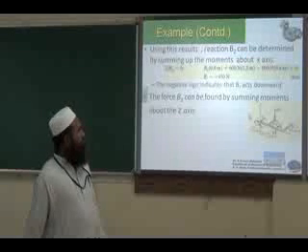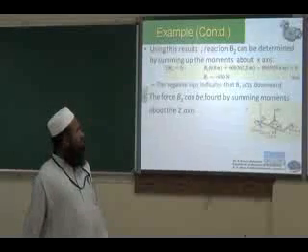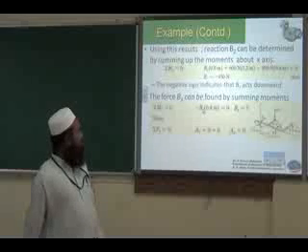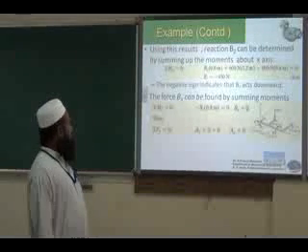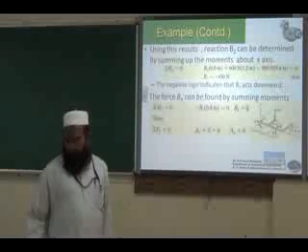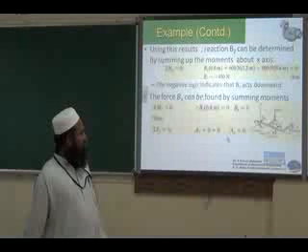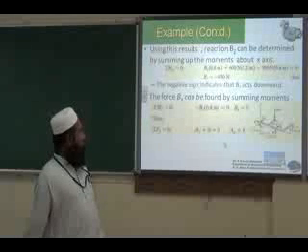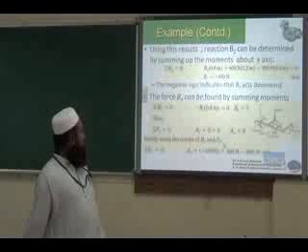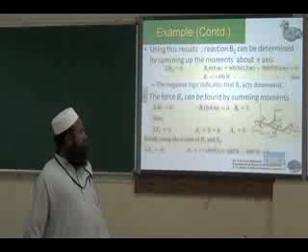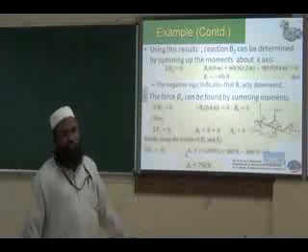So Bx can be found by summing up all the moment about Z axis. Similarly, Ax can be found by considering sigma fx. That is already 0. There is no force in X direction. Since Bx is 0, Ax will also be 0. Az can be found by considering sigma fz. So we consider forces acting in Z direction, and Az is found as 750 Newton.